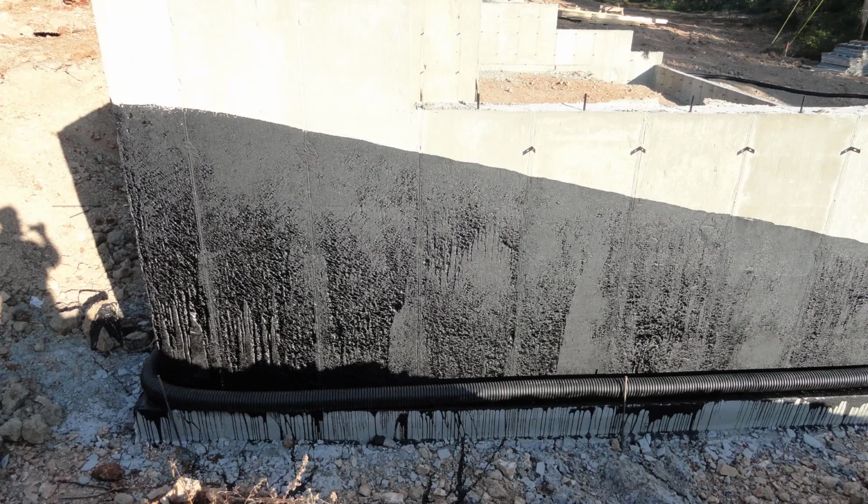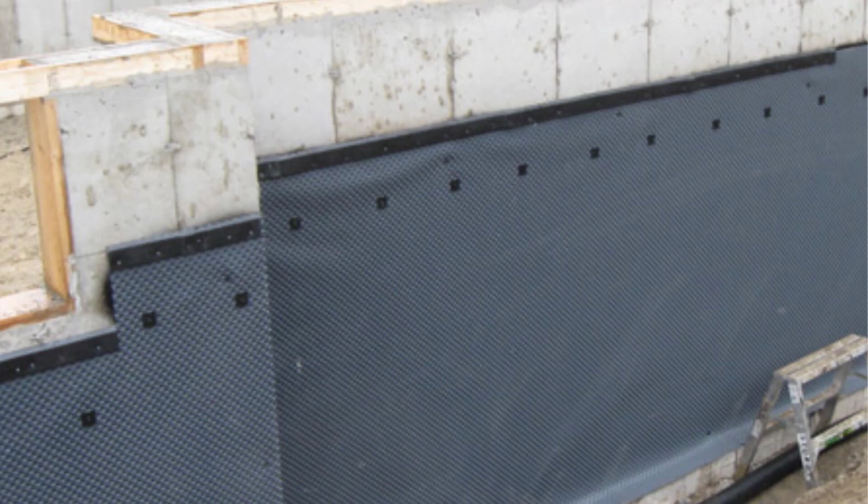Most modern foundations have a black asphaltic damp-proofing material applied on the exterior of the foundation wall prior to placing the backfill material. In areas where a high water table or other severe soil water conditions are known to exist, waterproofing is required in the International Residential Code. There is a distinct difference between damp proofing and waterproofing. Damp proofing is intended to keep out soil moisture, while waterproofing keeps out both moisture and liquid water.